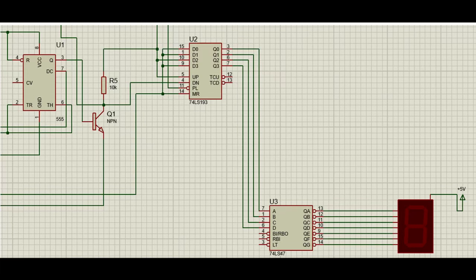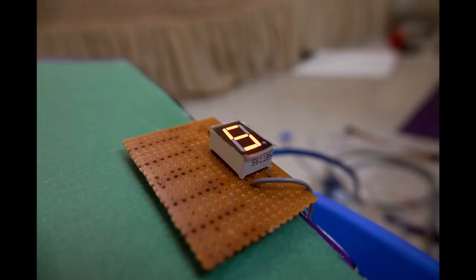We also made sure to check when green is on in that signal, so the timer only keeps time for the red light. The BCD counter outputs its current state in BCD code on pins marked Q0 to Q3. Now, to display it in human readable form, we have used a 7-segment display, common anode variant. In a common anode display, a segment lights up when 0 volt is applied to it, and it has a common 5 volt pin for all the 7-segment LEDs.